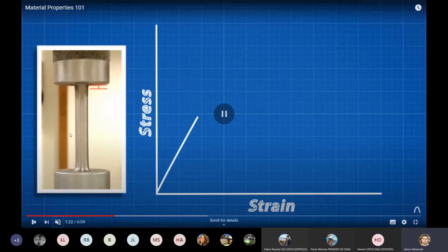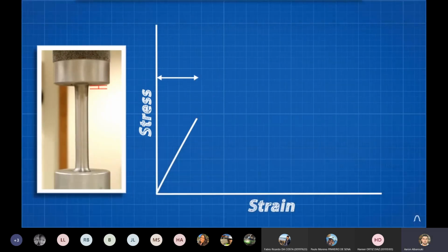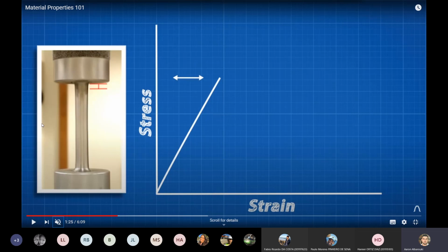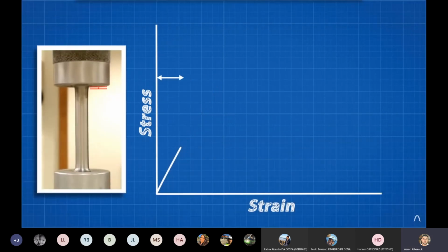You see the deformation on the steel. Can you see this red sign here showing you how much deformation? That's all within the elastic part. That's where the elastic part is finished. And we hit the yielding point. After this point, the steel, that's it, gave up. Doesn't give you any strength anymore. That's what we call the yield strength. If we stop, the steel will go back to normal. Okay, look at it. As soon as we took the force off, the steel will go back to normal.